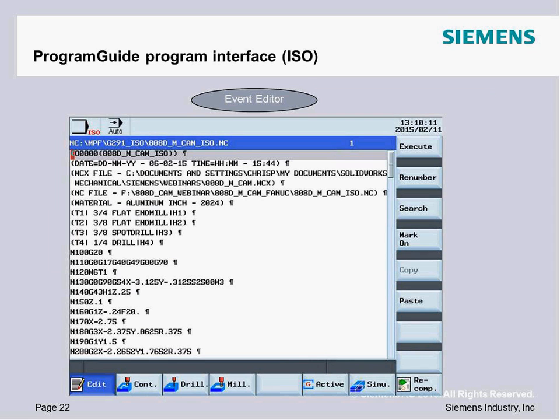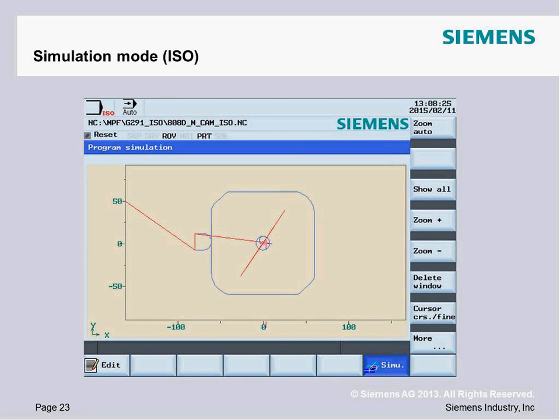Then we're going to look at the part program. For those of you experienced with ISO or FANUC style programs, you're going to see this is really posted directly for a FANUC machine. No editing needed per se, just no percent signs, and you just comment out the program number. You don't need the program number. It's a direct drag and drop into the system. See the simulation functionality.